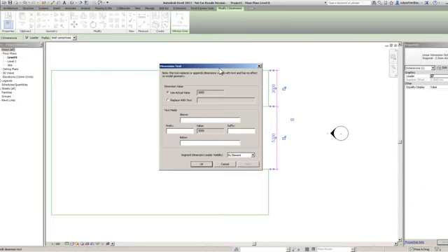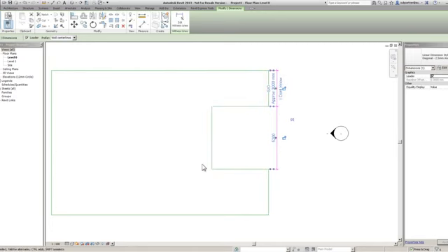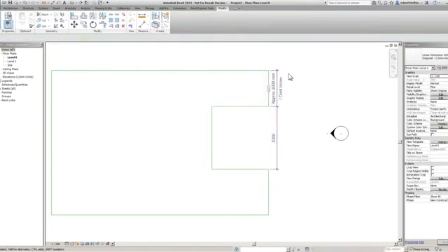Let's just show you quickly what this is while we're here. Basically we've got these two modes here, use actual value and replace with text. We've got text fields here, so just adding text above, a prefix, a suffix, and text below. As an example, I'm going to put structural opening, then approx. behind it, millimeters, and I don't know what to put underneath, so we'll just put that. When I press OK, as you can see, it's just added those.